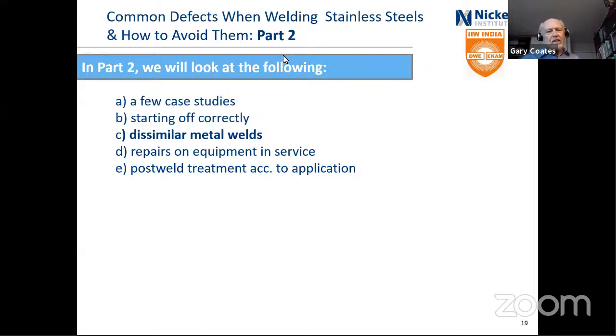These defects would have been detected by radiography for sure, but in plants where they aren't pressure vessels, where it's not required, it's not done. Radiography, of course, can be expensive, and if you actually use X-rays, you have to close off the area so that nobody is harmed by the X-rays. But yes, they can be detected by radiography, but not everything is radiographed.